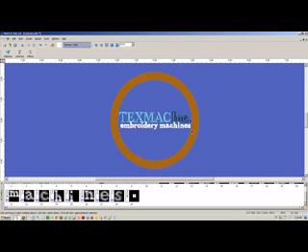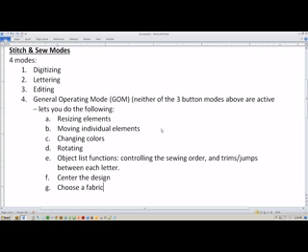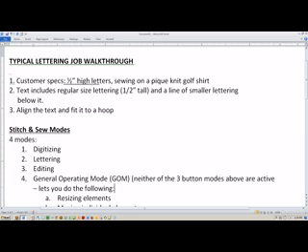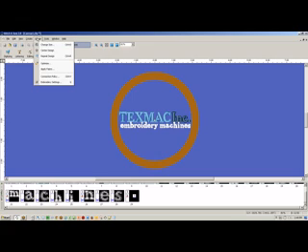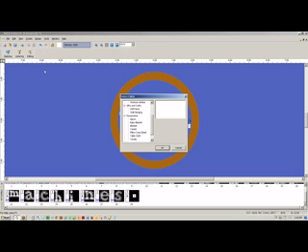So finally, what we want to do is make sure it's going to sew on the kind of fabric that our customer asked for. So in our scenario, the customer asked for a piqué knit golf shirt. So the way we compensate for that is going to Design and then Apply Fabric and find your golf shirts, in this case polo style shirt. You can see jersey knit, which is the smoother kind, or piqué knit, which is the bumpy open weave kind. Hit OK, and you'll watch before I hit OK, I'm at 3690 stitches.